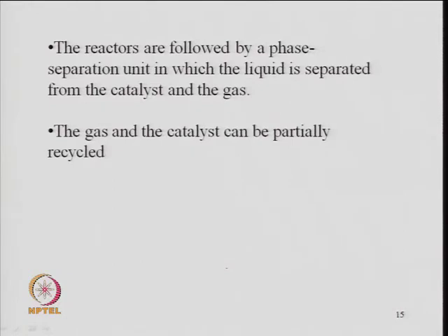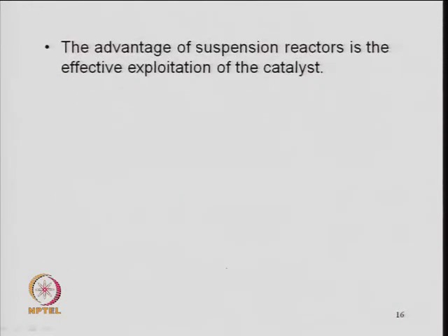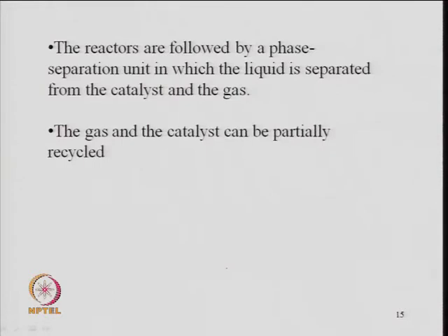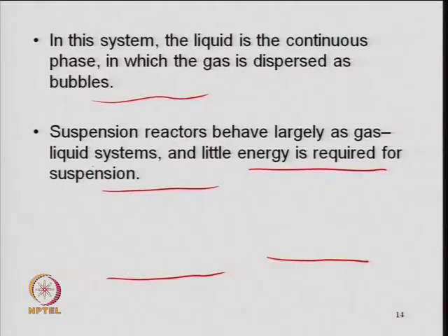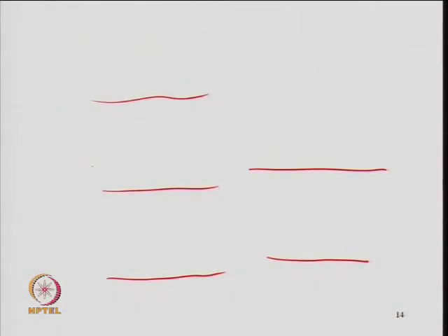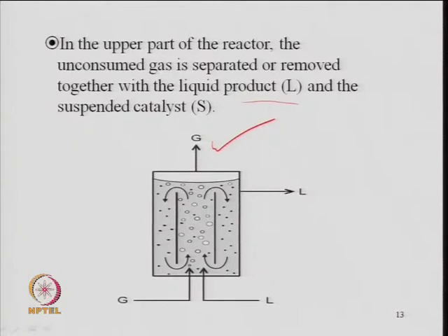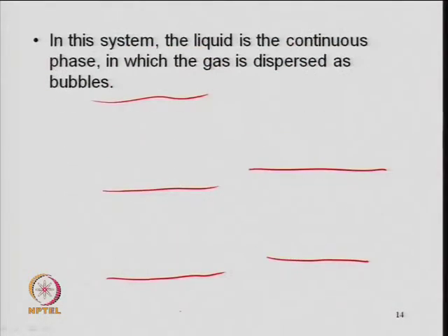So, the gas and liquid can be recycled during the system, which I said in the case of this reactor here. You can have a possibility of recycling this gas and liquid in the system, right. So, external or internal recycle, both kinds of possibilities are there, and the same thing in a bus loop reactor, where you have a jet and through that you can pass the liquid and gas.